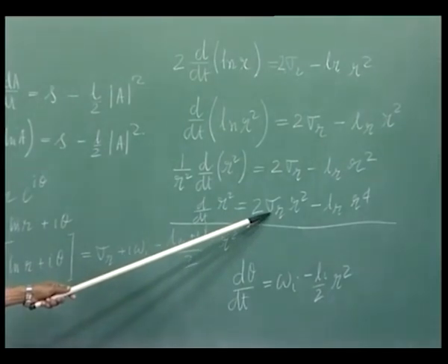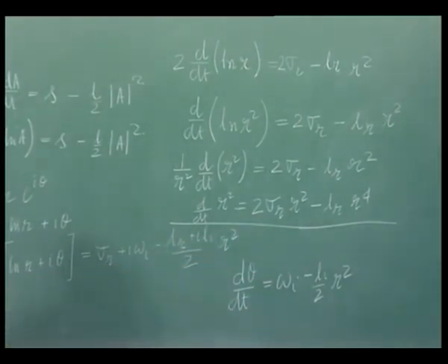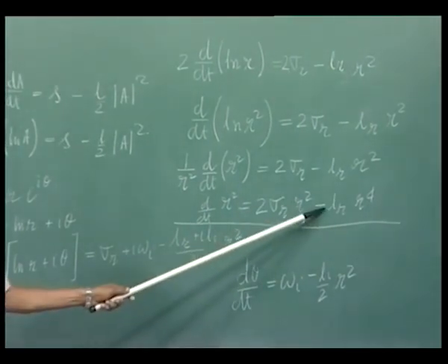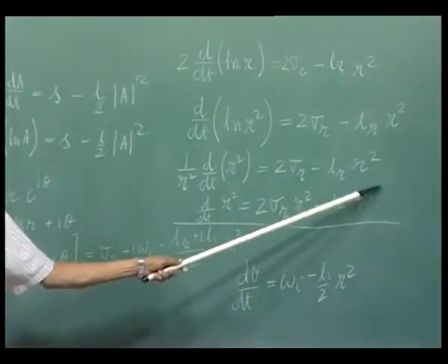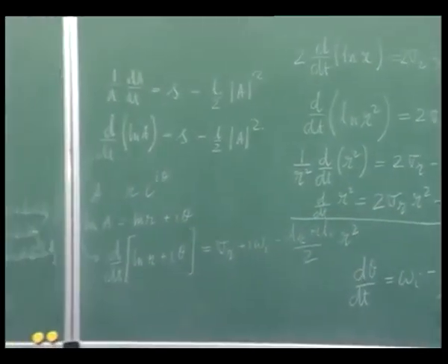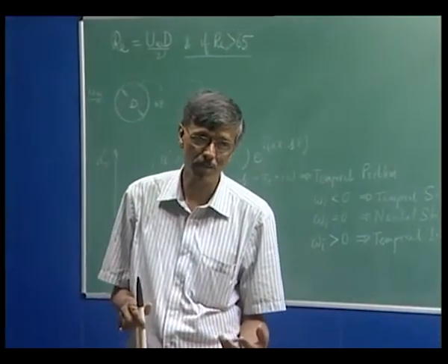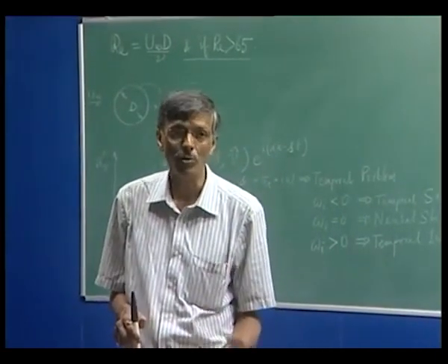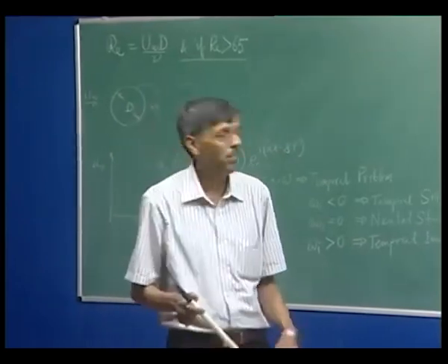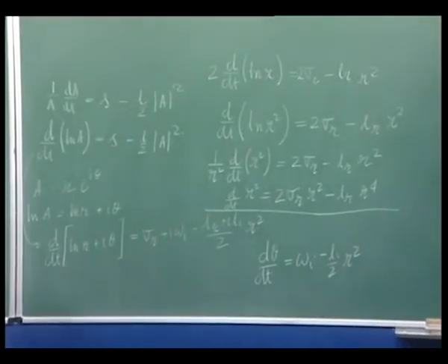This sigma r times R square. This could be negative. So what does it mean? It's linearly stable. However, if LR is negative and this quantity overrides this, then it will be nonlinearly unstable. So flows like pipe flow, wake flow, Poiseuille flow, that's where maybe one would be interested in the negative LR.